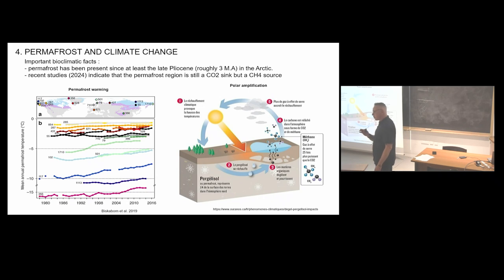At -2, we start to have a lot of unfrozen water content in the permafrost. And then it changes a lot of the processes. You can have water migration in your sand, in your soil, etc. And look at how flat it is when you arrive close to 0. So this is a problem with thermal monitoring. When we arrive close to 0, almost nothing changes in the temperature. We're extracting latent heat before phase change.